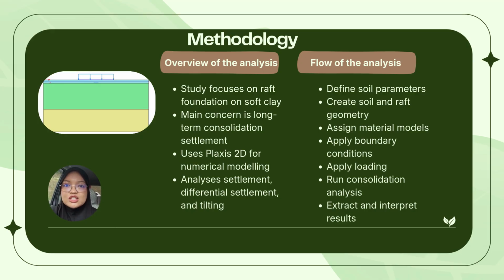The middle layer is soft clay under undrained conditions with a thickness of 15 meters, which is the critical layer governing settlement behavior. The bottom layer is bedrock under drained condition with a thickness of 13 meters, providing a relatively stiff support layer. The rough foundation is modeled as a plate element in PLAXIS 2D. It is assigned a plastic behavior to represent realistic structural response, with a thickness of 0.8 meter.